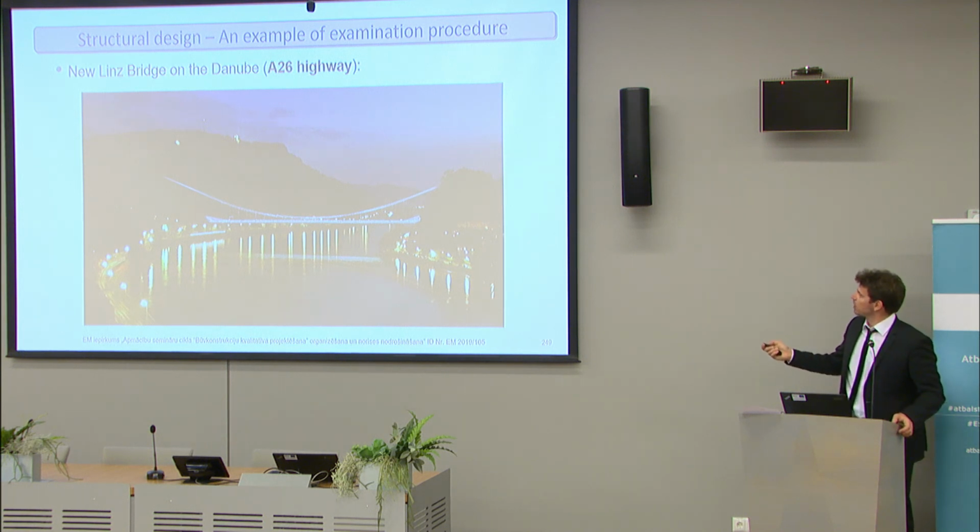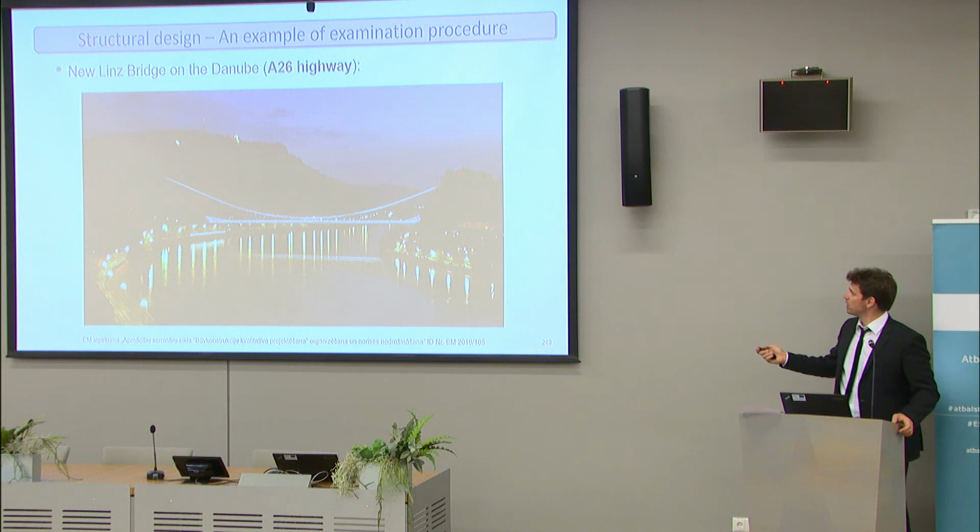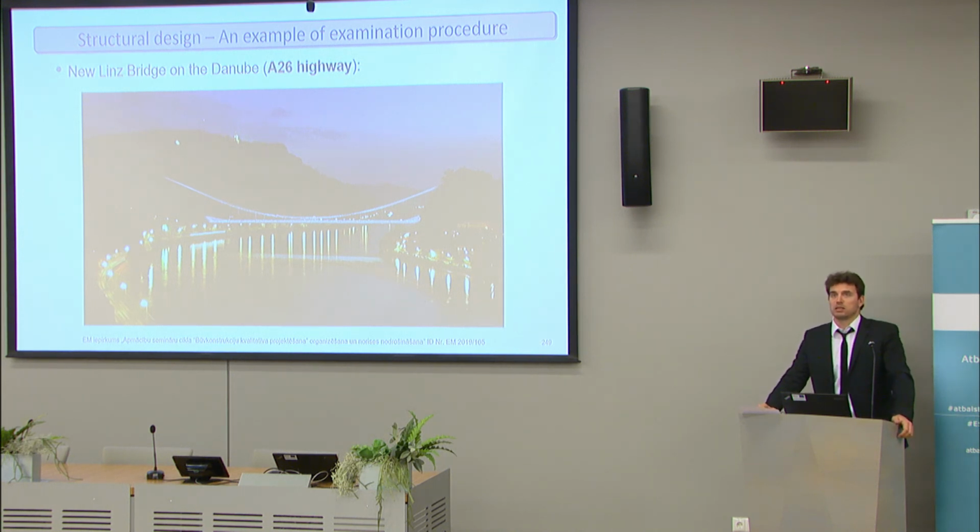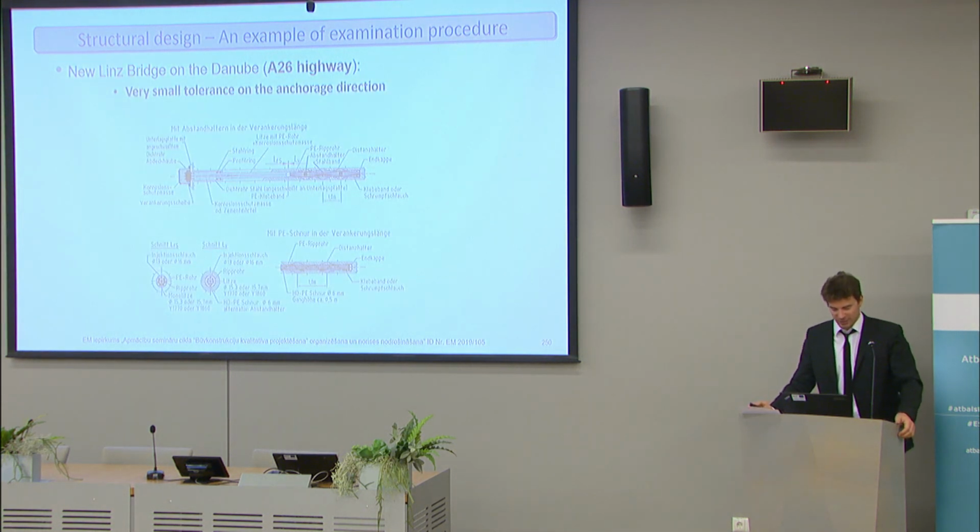At this time we are completing the anchorages here, and after we are going to start these here this winter. There are 110 anchorages on this side, and each one of them can actually take 3,300 kilonewtons. So it should be sufficient, I think. So these are actually the anchors. There are 11 strand anchors.